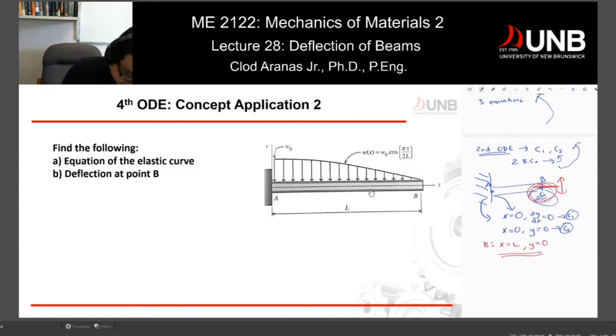So in this particular case, you can have 6 unknowns. And what are the unknowns that we can get from that? We have B sub y, A sub y, A sub x, M sub A, C1 and C2, because we are cutting